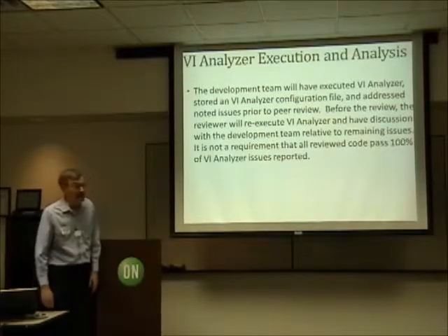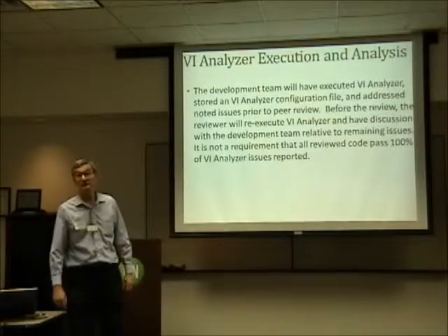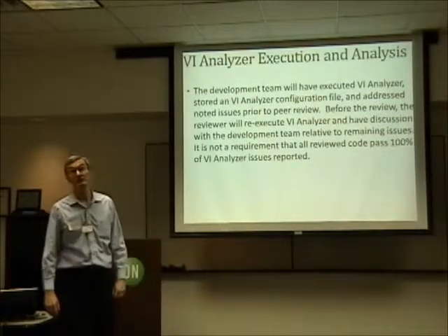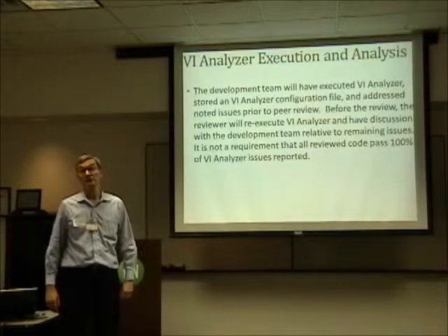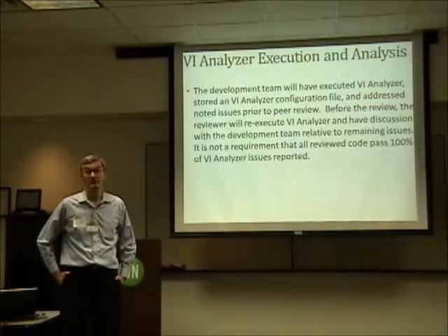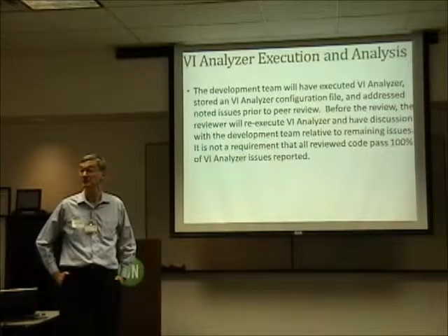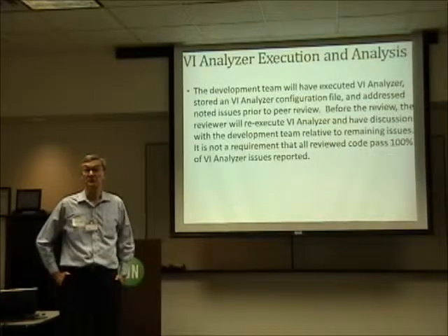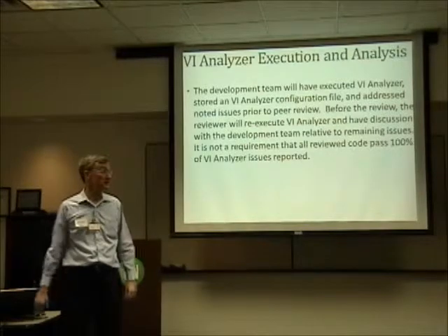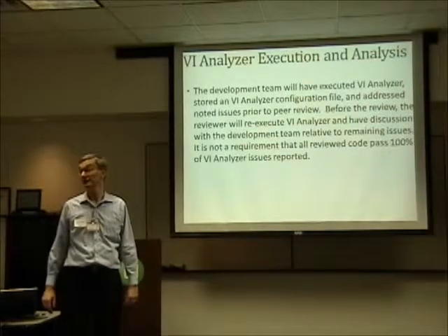We asked that the people that actually wrote the code run VI Analyzer because at least it catches the simple stuff. It doesn't do any good to ship something with wires under objects or similar problems. It's going to be very difficult for the maintenance programmer that gets called in because you're on vacation or you got pulled for a tiger team and you can't work on your own tester if they can't read your code. VI Analyzer at least catches a lot of the readability things. If you haven't used it, I'd encourage it.